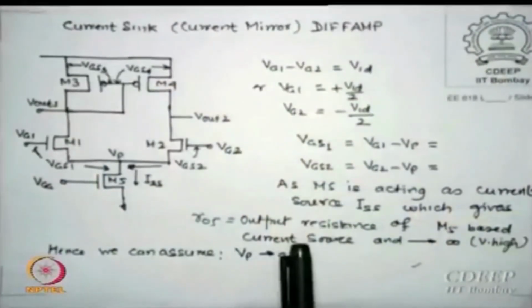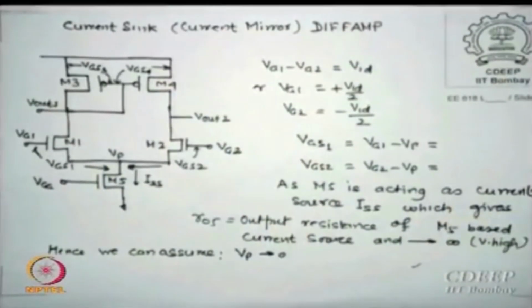So essentially VGS1 is VG1 and VGS2 is VG2. This is my statement. I may prove now that Vp has not moved. I did that earlier for a lemma, and I am doing it now for the real circuit. Please remember this statement I am making, and based on it I can assume Vp to be grounded as far as AC is concerned. Is that clear?